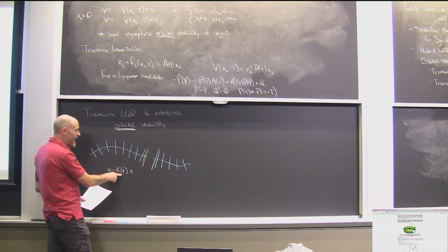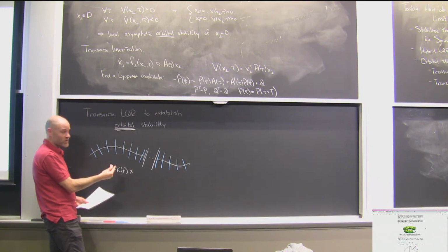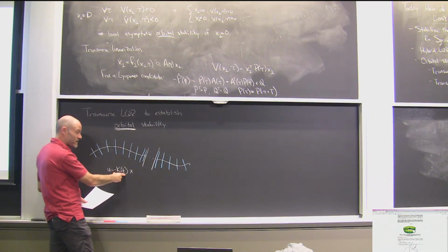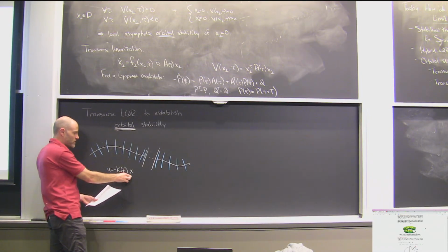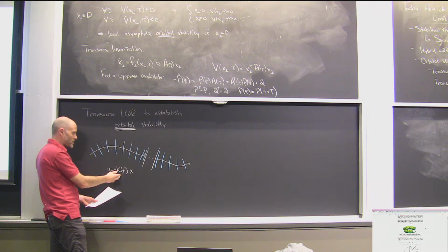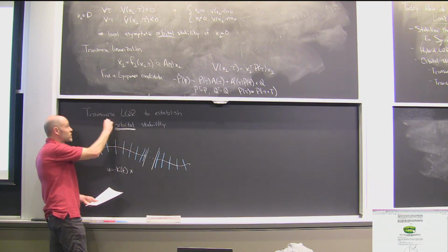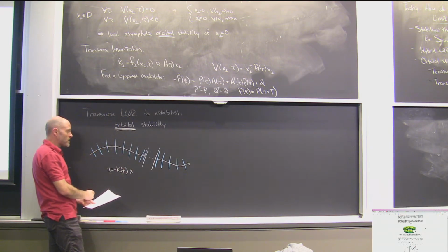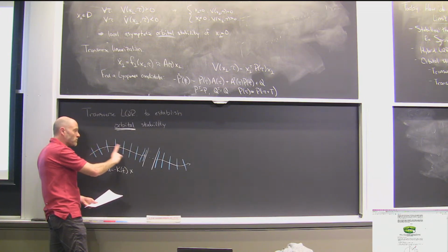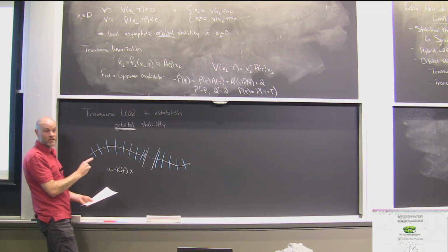But if you do it after the fact, you haven't told your synthesis about it, you can actually get, even for systems that exactly have a time varying linearization, unstable solutions like that. And you should think about the transverse coordinates version of LQR as exactly the form of LQR that is robust to that projection.